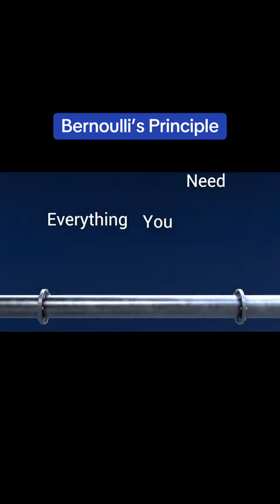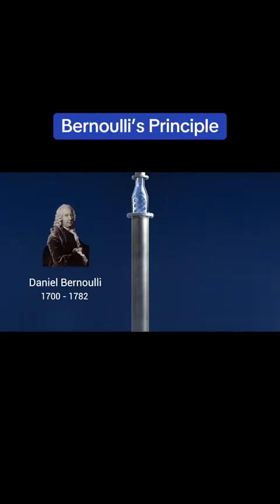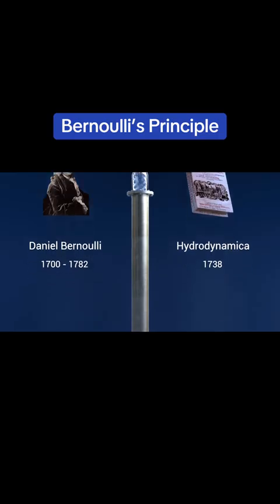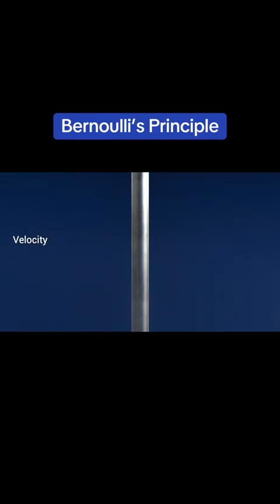On Engineeringness, we're diving into everything you need to know about Bernoulli's principle. What is Bernoulli's principle? The principle is named after the Swiss mathematician and physicist Daniel Bernoulli, who published it in his book Hydrodynamica in 1738. Bernoulli's principle is often explained by using the following statement: as the velocity of a fluid increases, its pressure decreases. However, this statement on its own is incomplete and often misleading.